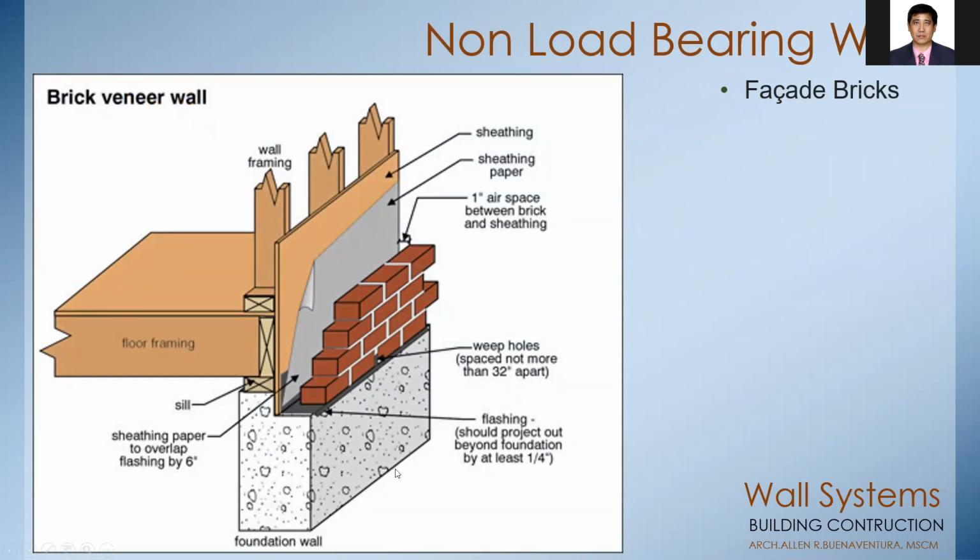As you can see, the foundation wall supports the main structural frame of the building, and there's a brick wall that is attached to the main frame of the building. So the brick wall doesn't carry the building; it carries its own weight, and it's only an architectural or attractive design that will be installed for purposes of aesthetics.